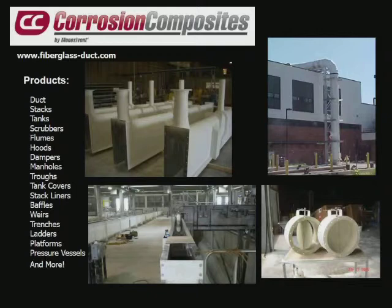The upper left photo and the one below it are from a project that we did at the Calumet wastewater plant on the south side of Chicago. There are 8 grit flumes used in grit removal, and they're about 200 feet long. They had to be abrasion resistant, and they had to be perfectly level on top and sloped from 18 inches on the shallow end to 36 on the deep end.